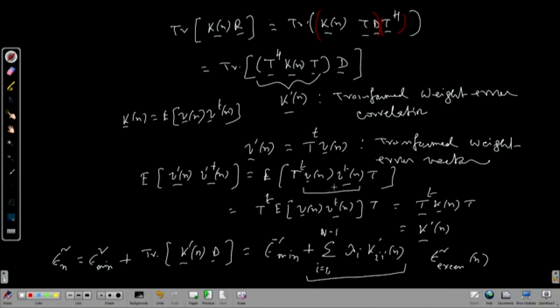In the autocorrelation matrix, I am taking the diagonal terms, and lambdas also are positive because they are coming from the capital R matrix, which is positive definite. So, these are actually positive valued sequences. If every sequence goes to a finite limit as n tends to infinity, that is in the steady state, then the summation also will lead to a finite limit.